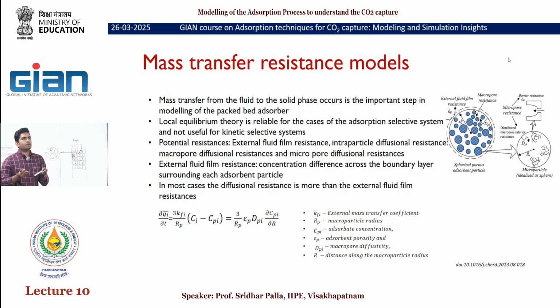This pellet is formed by a combination of multiple particles. A particle also contains pores, which are micropores. So micropores also contain a resistance, that is a micropore resistance. In case we are looking for a very accurate model, we need to consider micropore resistance, macropore resistance, and also the film resistance. We will look at them one by one closely. Mass transfer from the fluid to the solid phase is a very important step. That is where we consider the film transfer resistance in the packed bed. Local equilibrium theory is reliable only for adsorption selective systems.